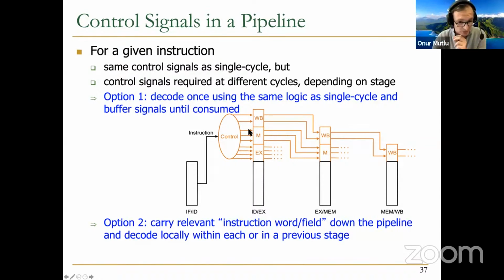So there's no need for the memory signals over here, for example, or write back signals over here. You carry execute and also the relevant fields of the instruction register. Here you generate the memory signals. So you have the memory, but you don't have the write back signal. You do have the relevant signals of the instruction register. Here you just have write back at the end.